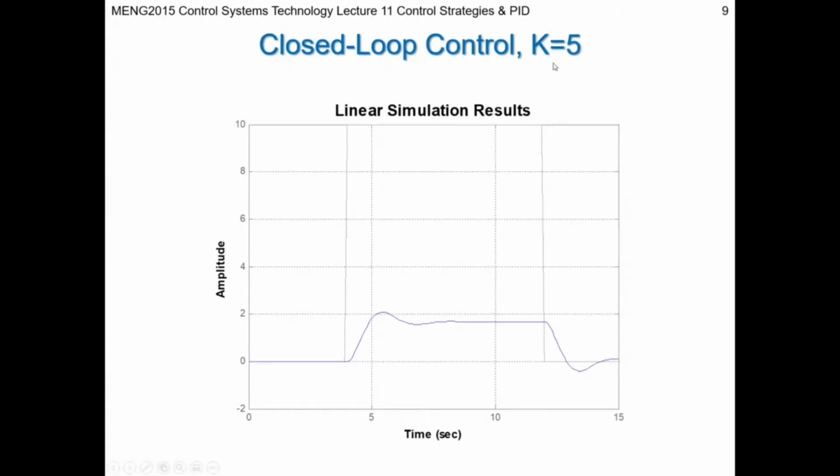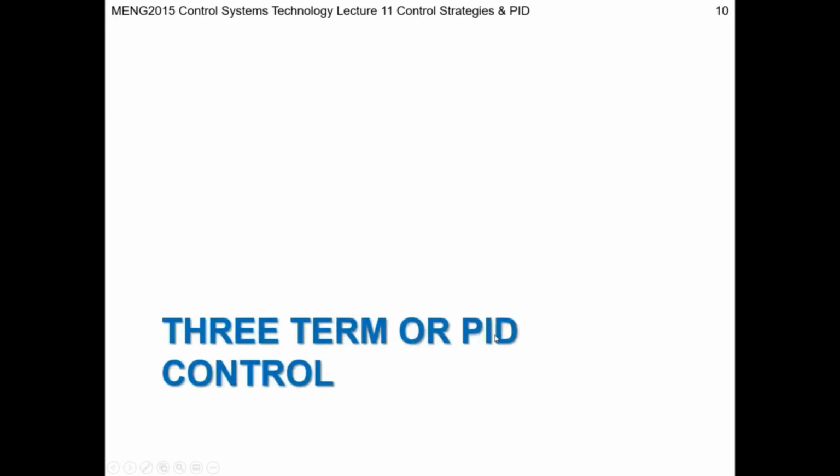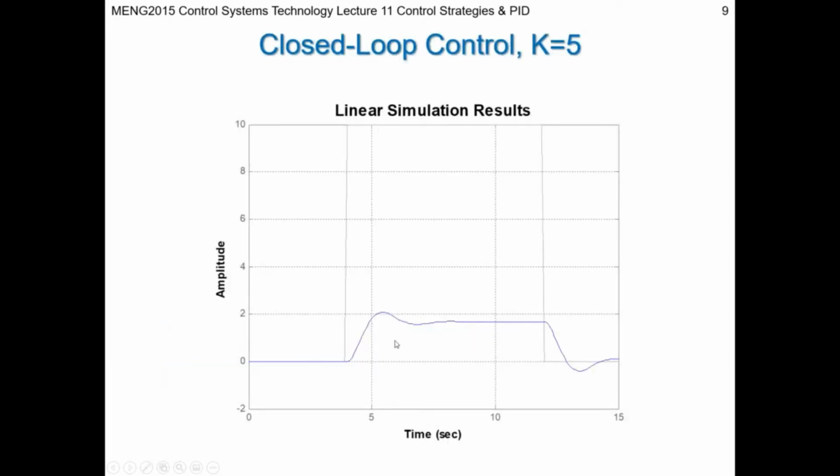If we continue to increase the gain K, then you can see that the amount of perturbation for the same disturbance of 10 acting at the same time is now much less. So we're kind of getting the system disturbance managed here, but we've still got some going on. Ideally, you'd want to get this system disturbance response as close to 0 as possible.